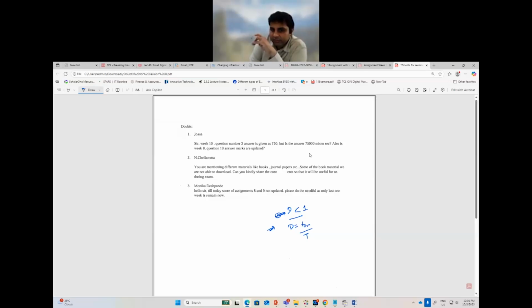That means if it is 75%, my duty to be considered when using this formula is 0.75, and that is when you will get T on to be 0.75 times 1 millisecond, which gives the value of 750 microseconds.